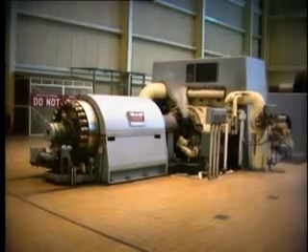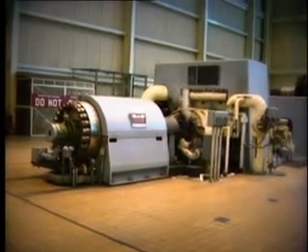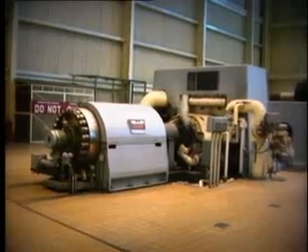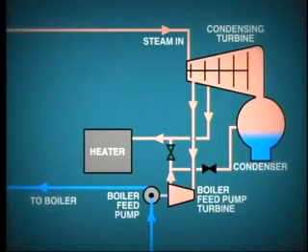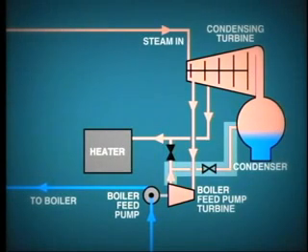On large turbine generator units, the feed water pumps are sometimes driven by steam turbines using extraction steam or cold reheat steam. The discharge from the turbine drive may then be piped to a lower point of extraction for further heat utilization. Alternatively, it may be piped to the condenser so that the condensate may be recovered even if the latent heat is lost to the cooling water.